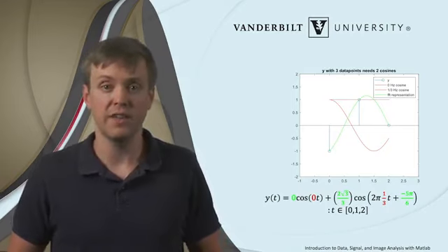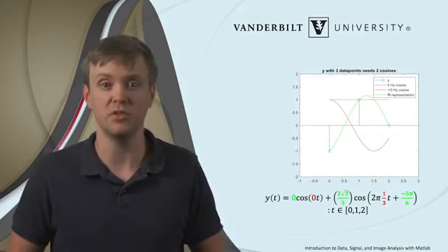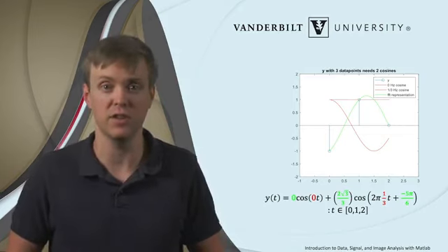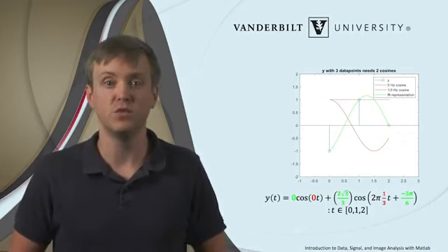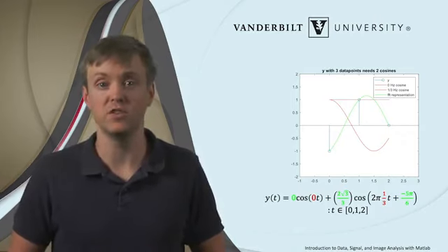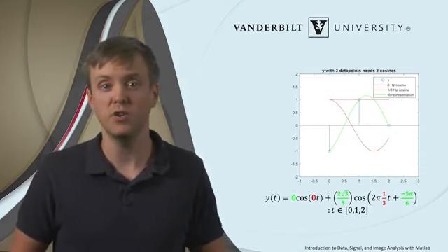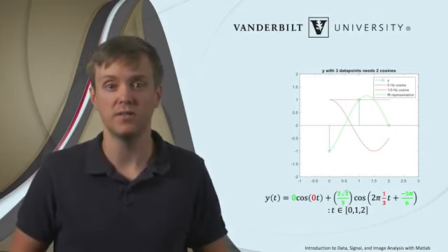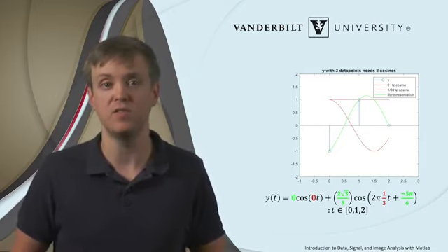We are in fact solving a linear system for the complex numbers used to define the amplitude and phase of cosine functions used to represent the signal. So this explains why a signal with 3 data points needs 2 cosines. With 2 cosines, we have 3 degrees of freedom in our cosine fit, with the amplitude of the 0 hertz cosine and the amplitude and phase of the second cosine.